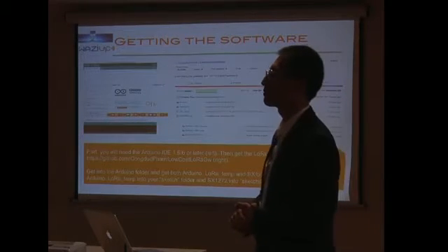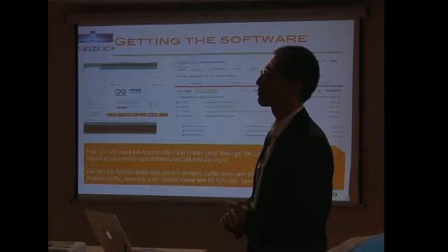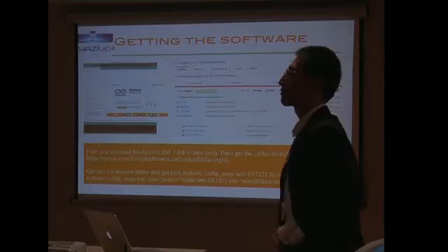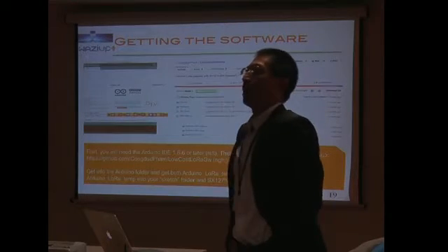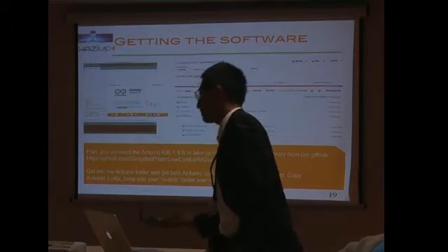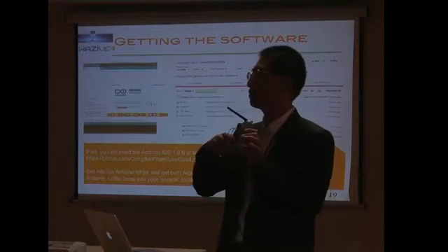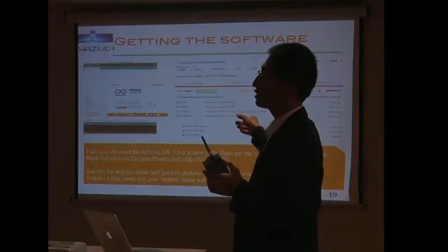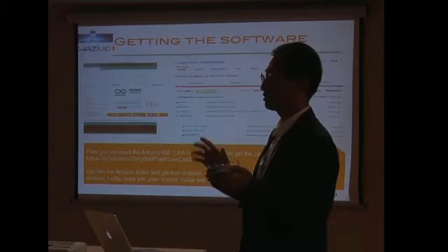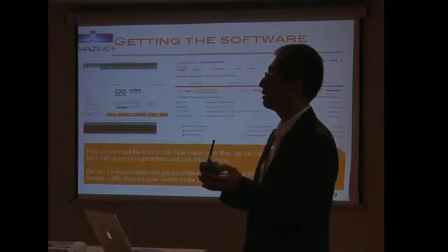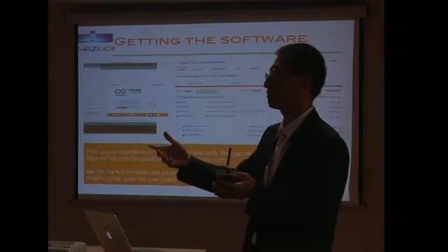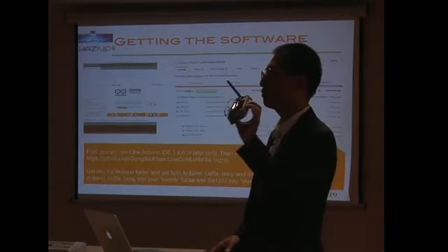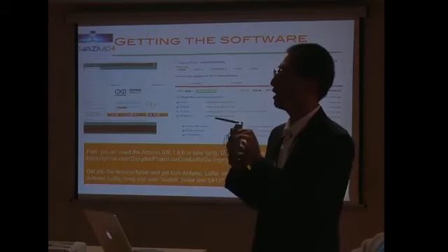Does it make any sense to think about SMS messages as another way to communicate, because now there are some approaches that can use SMS? I agree with you, but still, SMS means that you have a 2G system, SIM card and so on. If you look at the consumption, you're not going to have a consumption of, let's say, 20 milliamps. You're going to have a consumption of 200 milliamps, so at least 10 times more. So you're not going to run on a battery for a year, like 4 AA batteries like this.